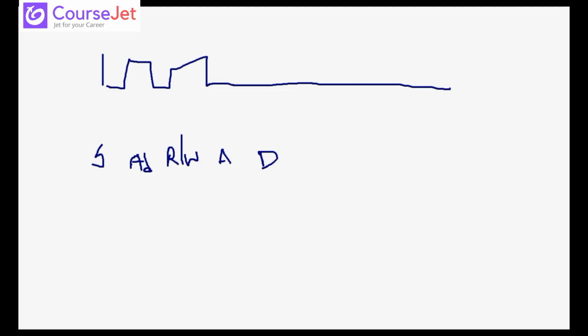Now here you have one more thing. First of all, when I have multiple slaves, suppose I have 2 SD cards, first I need to give the address of that SD card. So the first address indicates the device address. That device address is provided by your manufacturer. So this device address is to select which slave you want to work with. I want to work with the first slave. We have 128 slaves, right? 128 devices are connected. So which device do you want to work with?